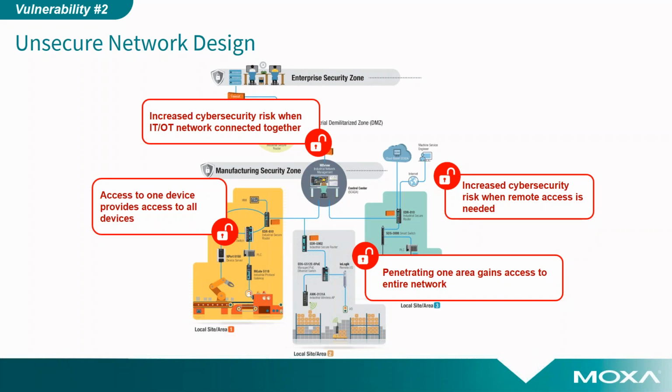And then remote access, whether that's site-to-site remote access within your own company, or access that you're providing to maybe some of your maintenance technicians to get into the equipment after hours remotely, or a vendor that's doing some troubleshooting or maintenance on your behalf. Make sure that the connections into your system are authorized, that the people using them are also authorized, and you're validating that, and then that those connections are encrypted so that the information that is sent remotely is not interceptable.